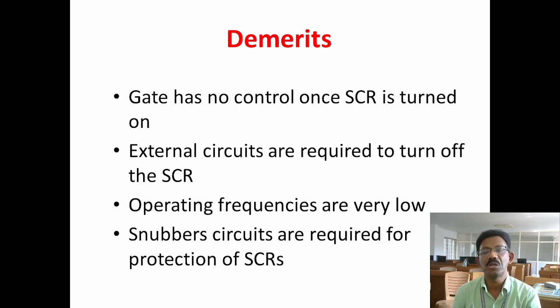Then demerits. Gate has no control once SCR is turned on. Gate is used only to turn on the device, not to turn off. That is one major demerit. Then external circuits are required to turn off the SCR. If you want to turn off SCR at our desired instant, we need to connect some external circuits to make the SCR turn off.